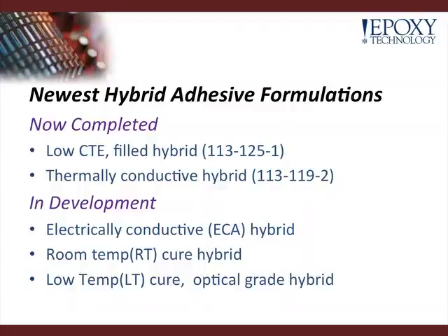And in the future, we plan to develop an electrically conductive UV hybrid and room temperature curing versions of UV hybrids. These would be systems that could be UV initiated and then left on a shelf or shipped to customers to allow to cure. We have one of these in the pipeline, and I will say they do take about 5 to 7 days for that thermal post-cure to occur.